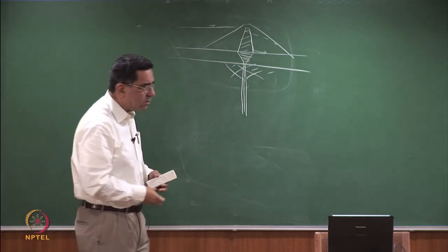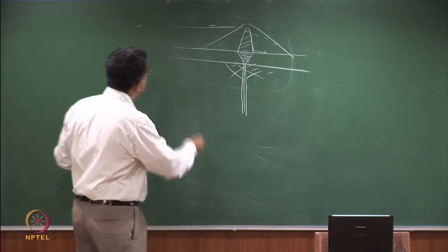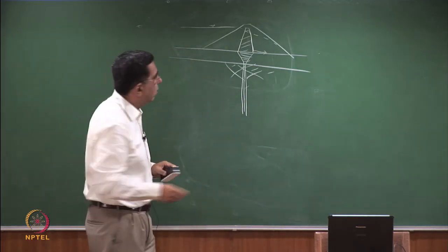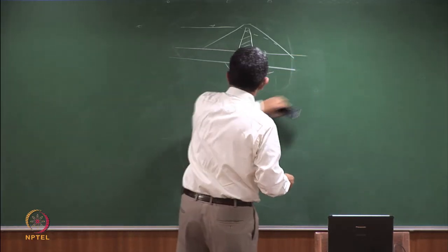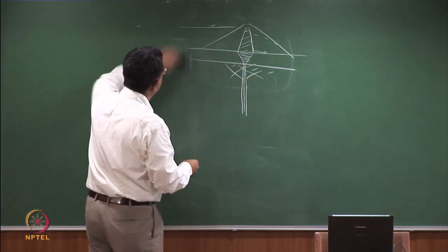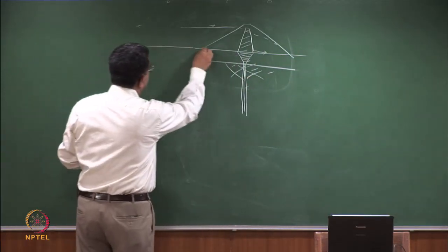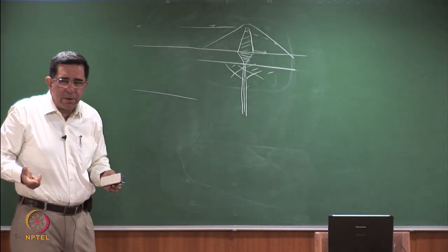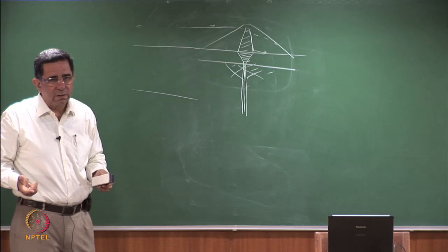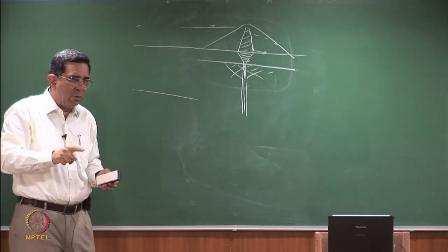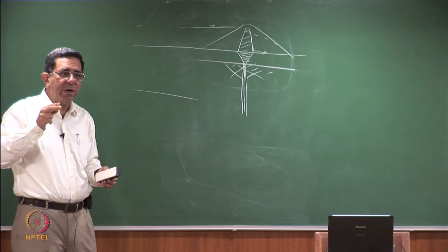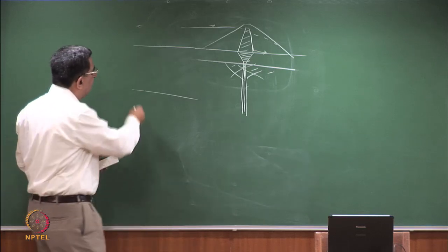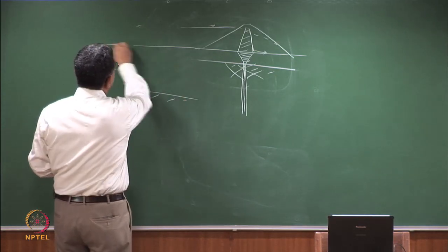So the first thing that you see here is, of course, when the location of the rock is deep below. Suppose my situation was, this is the base of the dam and my rock is here. Now making a 20-meter deep cut-off trench is very difficult, right? So I have the option of grouting or I have the option of making a vertical diaphragm wall, a vertical cut-off wall. So when the rock is deep below and my dam is way up there,